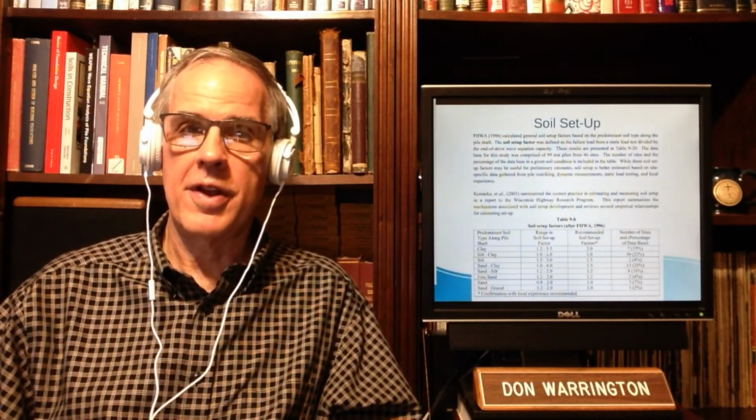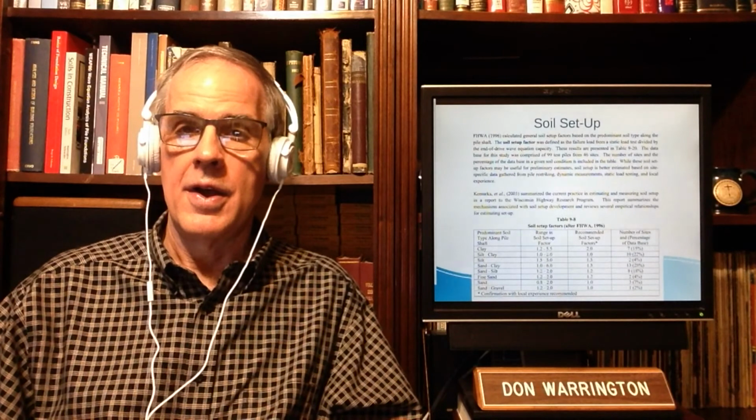So it was everybody's pleasant surprise. Well, why do we need this big of a hammer? Well, basically, most of us had assumed setup factors in the 2 range, when in fact, one geotech who had a lot of experience in the bay mud said that setup factors there are 5. So that pretty much settled that, didn't it? We could have used a smaller hammer, but then again, we did not. So setup can do some strange things to you if you're not really careful. And that's another place where experience is important.